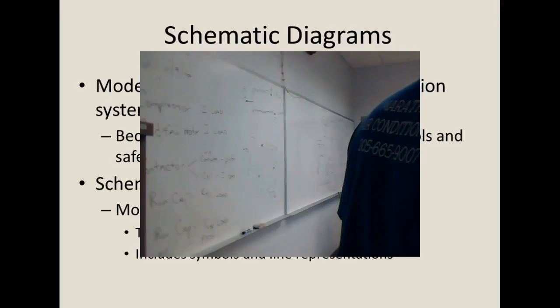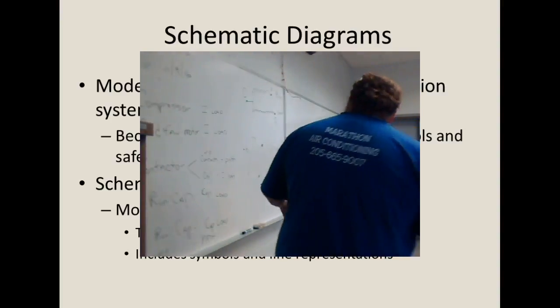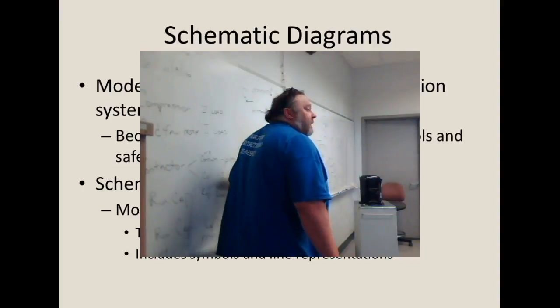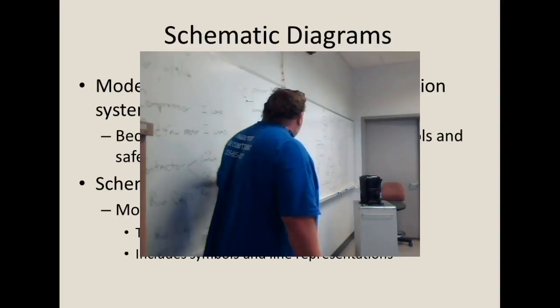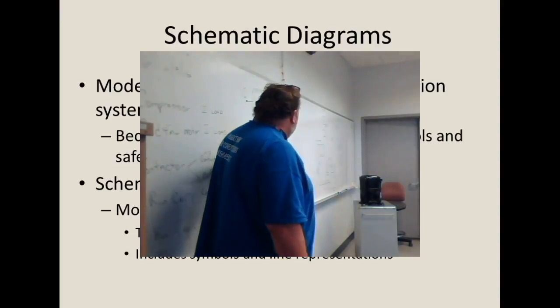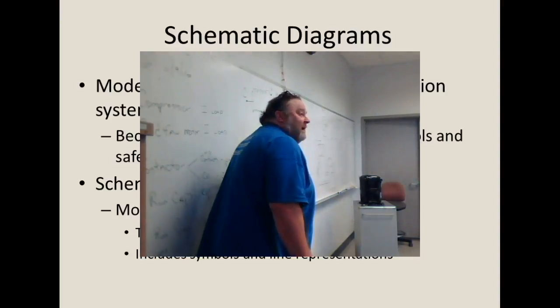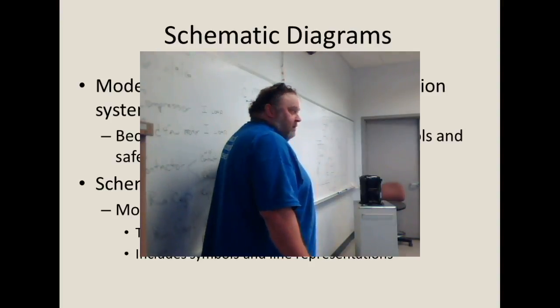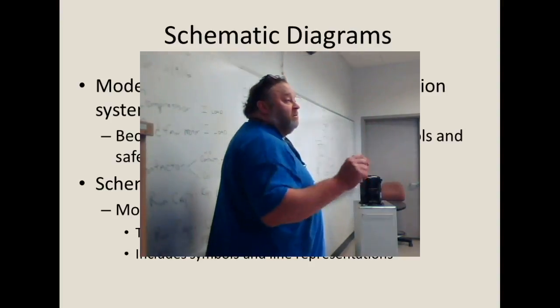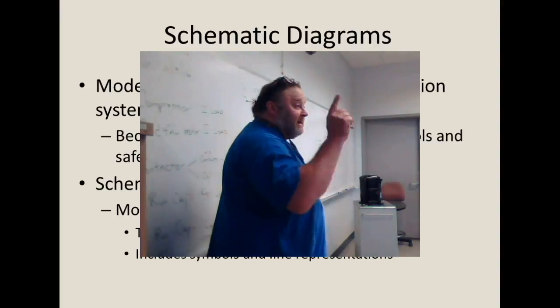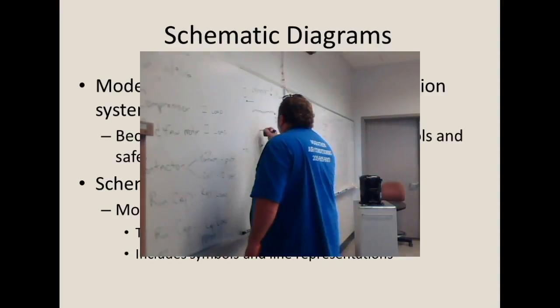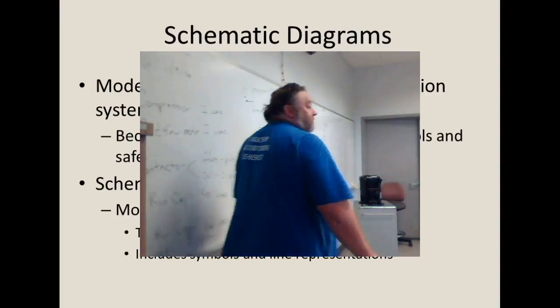Now, what terminal is not used in that reading? To get this reading, I'll use these 2 terminals, didn't I? And that was the highest. If this had been the highest, then these 2. But to get this one, I didn't use. So the first thing is, when you find the highest one, the terminal not being used is common. That's my first rule.